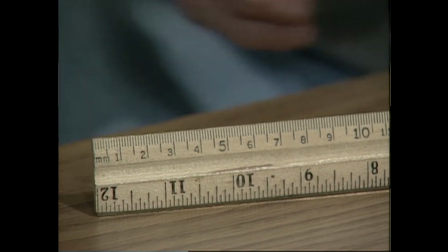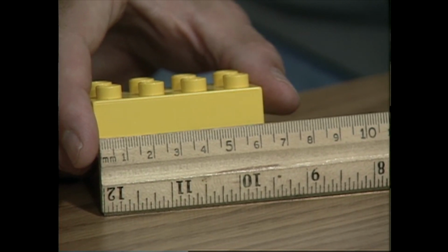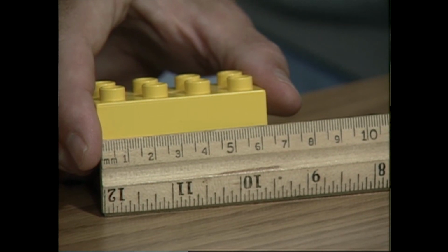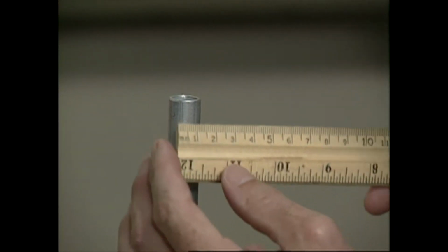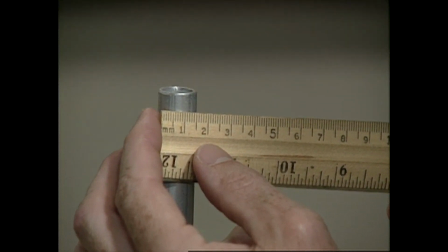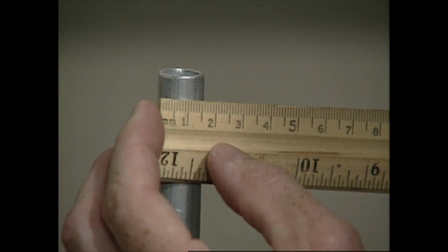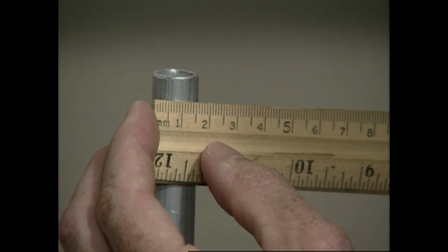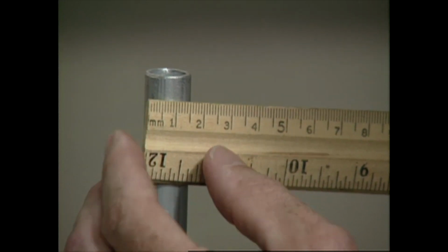Now, rulers and tape measures are good for measuring linear distances where you can actually put the edge you want to measure right up against the scale, so you can get a fairly accurate measurement of the dimension. Now, you get into trouble if you try to measure something like the diameter of this pipe with a ruler. The problem is that because you can't put the edge of the pipe right up against the ruler, you run into what we call parallax error. If you move your head, what happens is that the apparent edge of the pipe will move around, so you can't get a very accurate measurement.